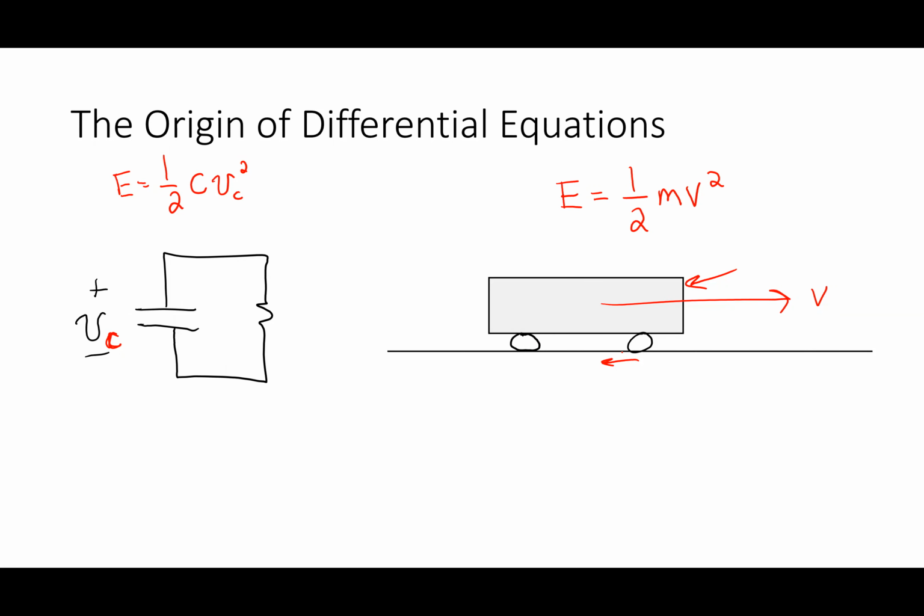So if I have this basic relationship here, one thing that's always true in any of these things is the voltages and the speed here always have to be continuous. I can never have big jumps. If there's a sudden jump in a voltage on a capacitor or a sudden jump in the speed on this thing, there has to be a change, okay? And that change, like if I stuck a screwdriver across here, I would get a sudden flash of light or something like that, where the energy that was stored in the field becomes light. So that principle is really important, right?